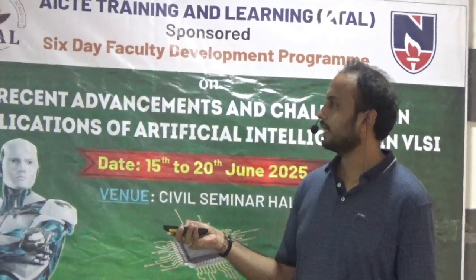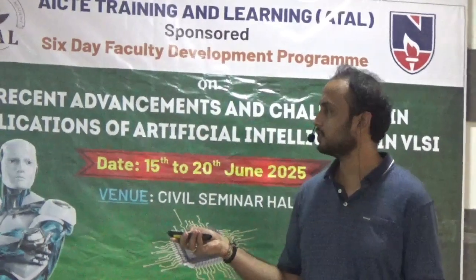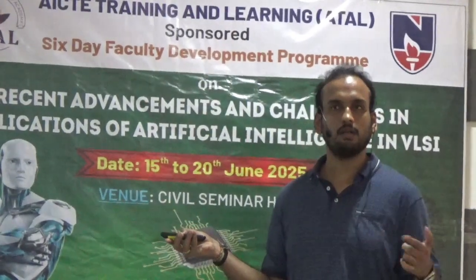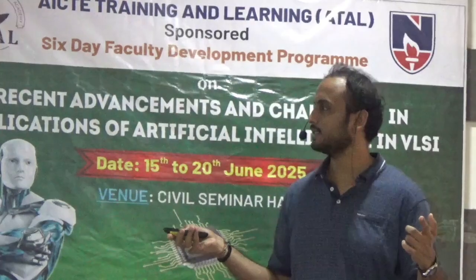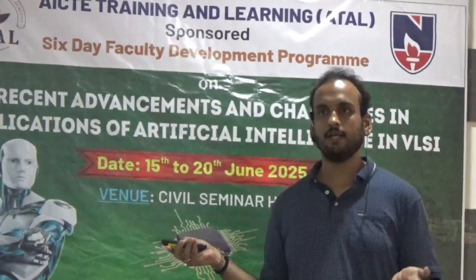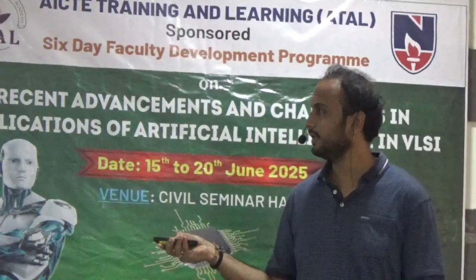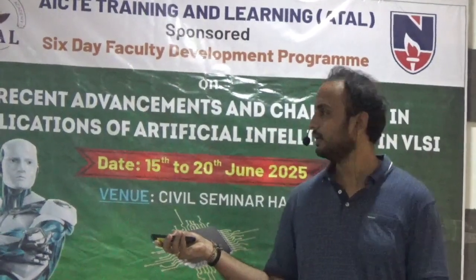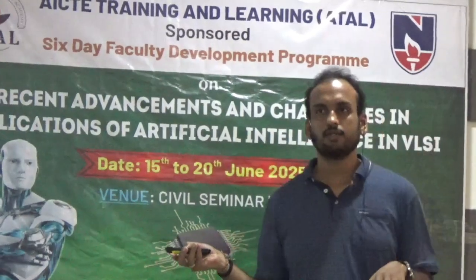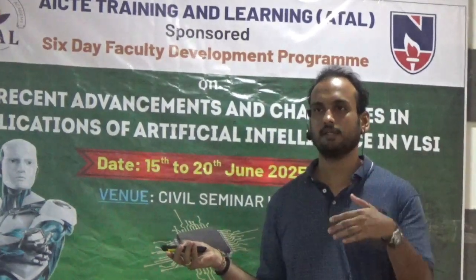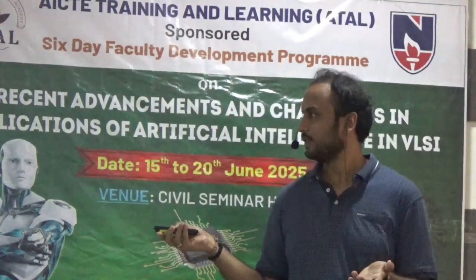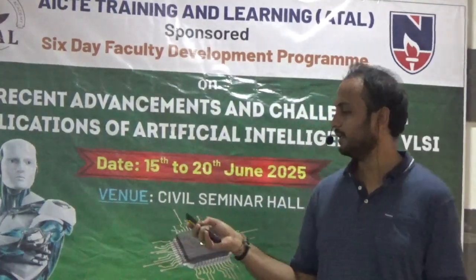But what happens to the gate length? The gate length is almost fixed. If you recall, you start with 180 nanometer. Let's say we start with some 1 micrometer, we come to 180 nanometer, 90 nanometer, 65, then it will saturate to some 20 nanometer. So the gate length of the transistor is always fixed beyond a point. If you talk about 3 nanometer or 5 nanometer, it's not actually the gate length. So this is almost fixed going through the years.